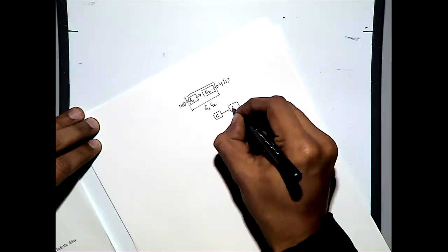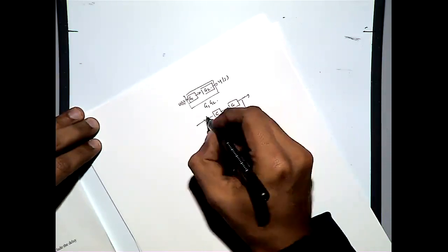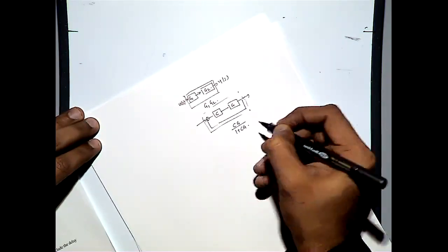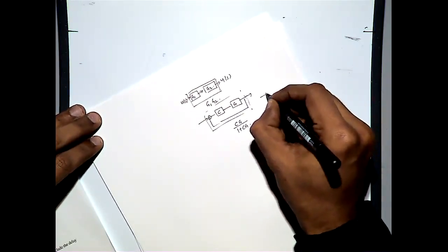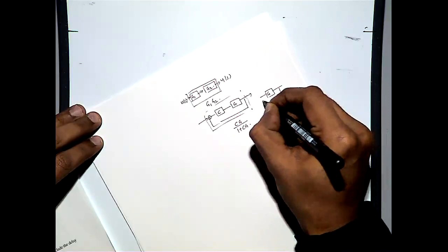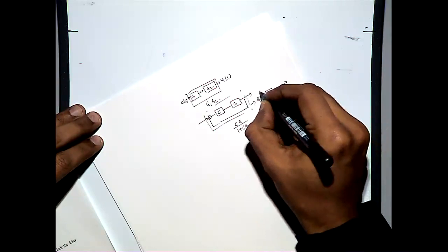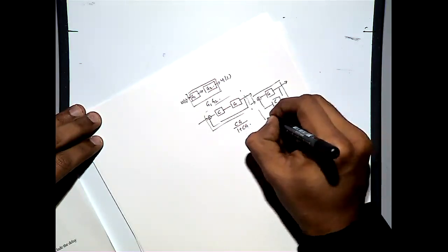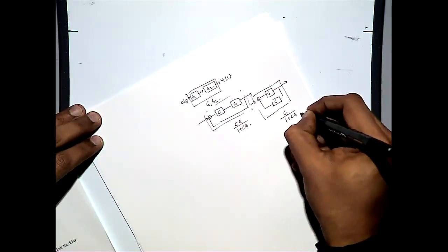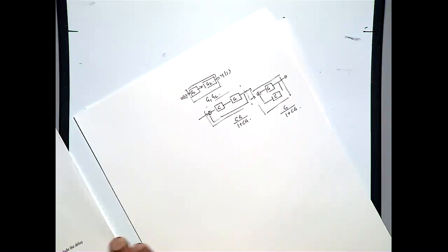If it is a closed loop system where you have C and G and you give a unity feedback to the system, the transfer function is given by CG divided by 1 plus CG. In the case where you have another type of closed loop, where you have a controller here, and you have a feedback here, the equivalent transfer function for this case will be G divided by 1 plus CG, right? So let's apply this to this problem.